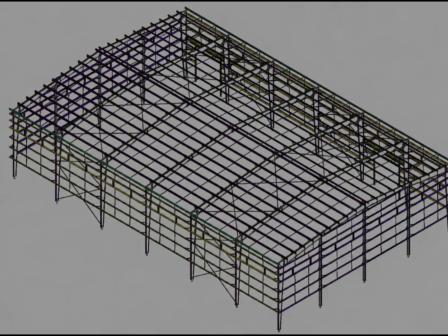Now focus again on the roof purlins. The purlins form the repeated secondary roof framing system. The sag rod arrangement is understood in relation to these members. This relationship is important because the sag rod is not an isolated component. Its location is determined as part of the overall roof framing arrangement. So, when tracing a sag rod in 3D, do not look for the rod alone. Look for the relationship between the rod and the surrounding purlin framing.